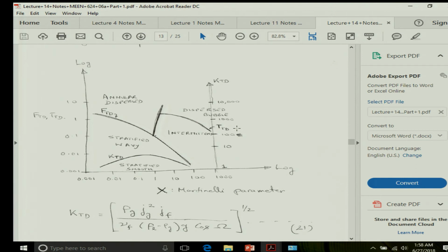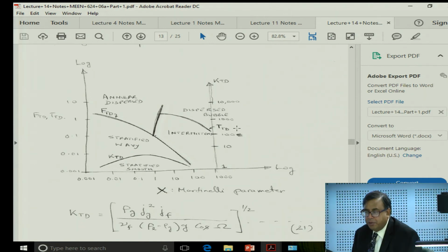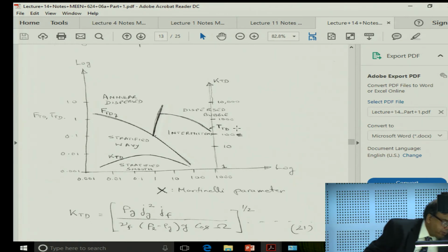So, you can use this particular flow boiling map. I forget what diameter pipe they use, but if you go look up the references they will tell you what diameter pipe was used and what Reynolds numbers and flow rates were used. So, as long as you are within those zone of those flow rates and Reynolds numbers, you are fine to use these equations. But if you go outside of the range of these equations, then it becomes very uncertain that the predictions you are making are correct or not. And so, in that case the only recourse is to go and regenerate your own flow boiling maps and then use that. Okay. So, any other questions?